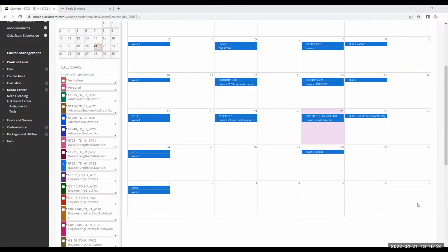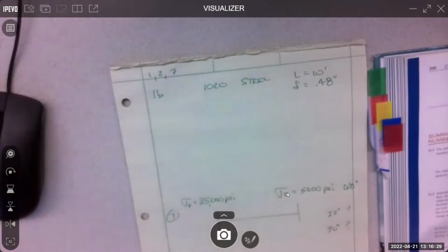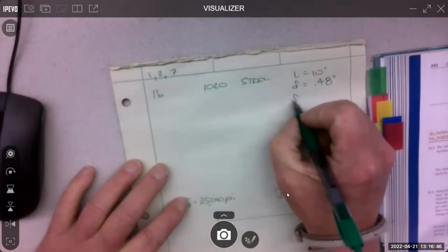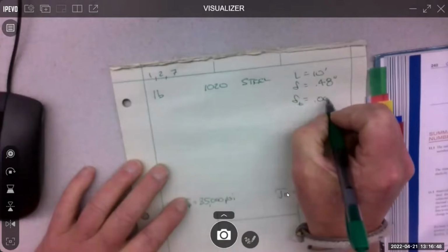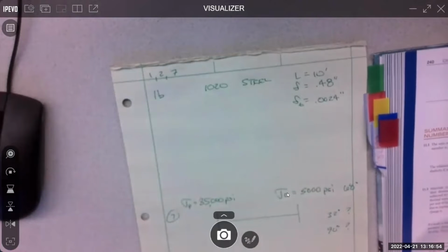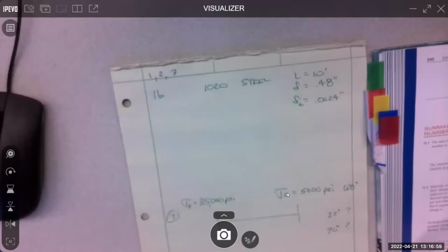All right, let's go over the homework. I wanna do 1B. So 1B, A just asked you to compute the longitudinal strain in the bar. I think everyone probably could do that just with PL over AE. But B says if the transverse deformation of the rod is 0.0024, and the rod, we didn't have the, maybe I do need to do that. Well, we'll see. Compute the Poisson's ratio for the material.